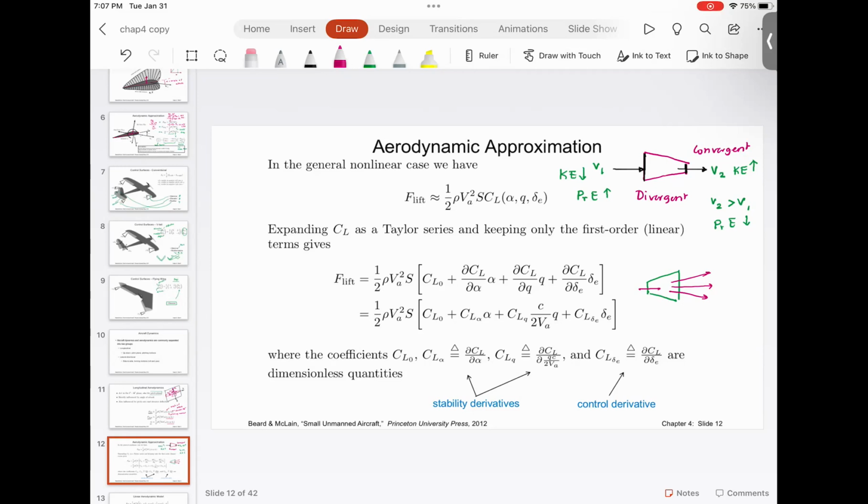It becomes like a compacted mass. And if you push that compacted air through this converging, diverging nozzle, when air reaches the diverging part, it expands, and that gives the higher velocity.